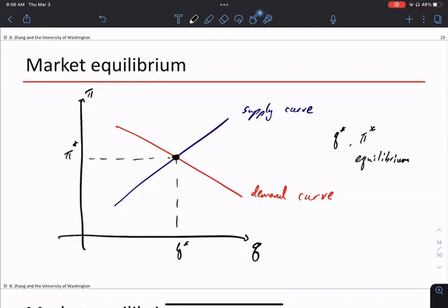So this is actually what happens. You want to calculate the price of power at a location. You ask all the generators to tell you what their supply curve is. If you are a generator in the market, you have to tell the market operator your supply curve. The market operator puts all the supply curves together into one big supply curve. You look at the demand curve, you cross them, you get a price out. Okay, so that's how we compute this kind of equilibrium.